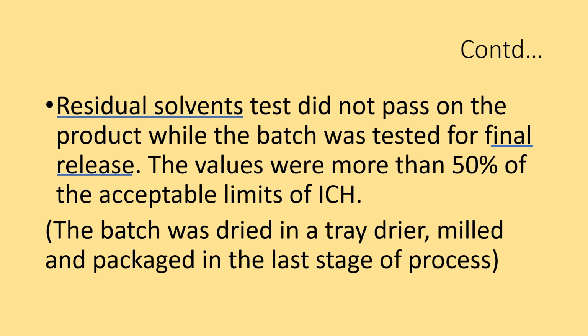Go one more step backwards. The drying time depends also on the wetness of the cake unloaded from the centrifuge, which goes for drying. So the investigation should focus on this aspect and check whether or not the centrifuge was spun properly to achieve the target wetness for the cake.